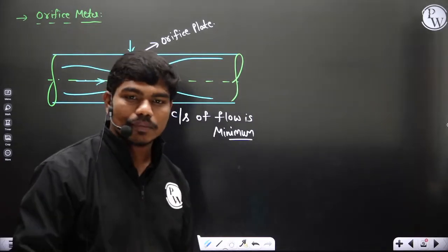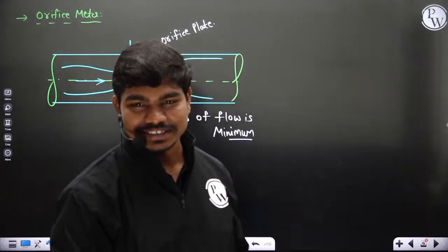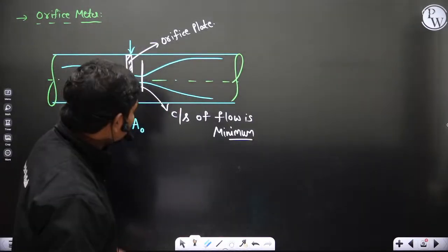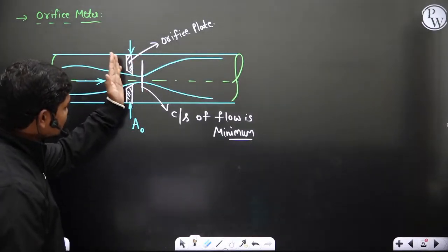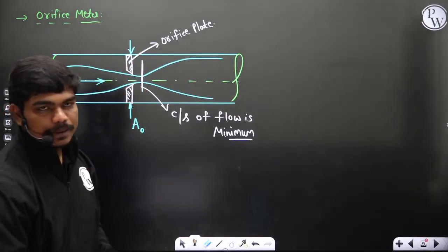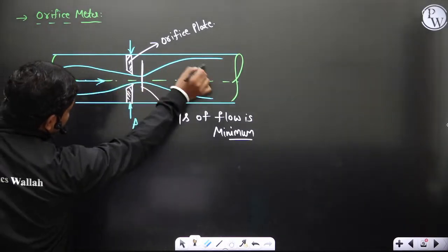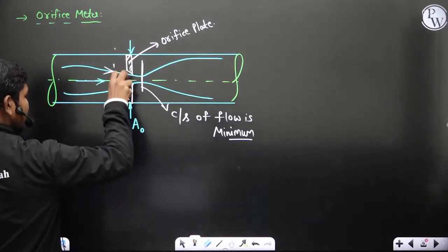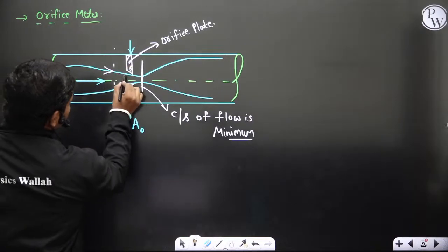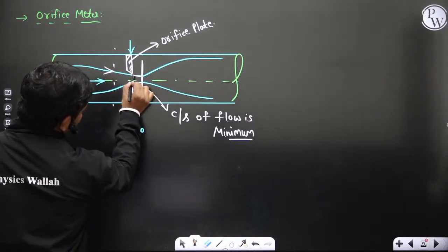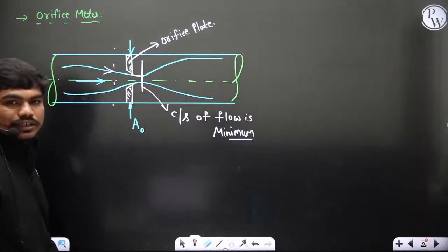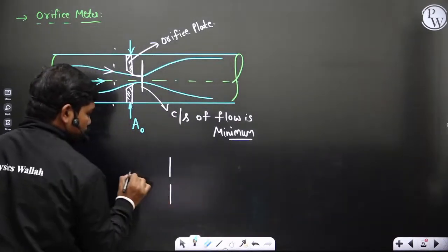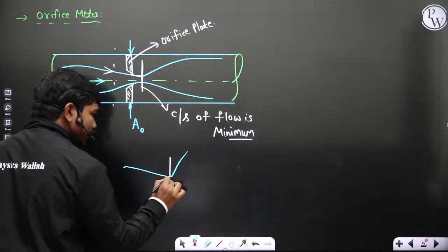If the calculation is complicated, you can use a bit of trigonometry, like we used in hydrostatic forces. Now see here, this cross section of the flow is minimum somewhere after the orifice plate, but not at the orifice plate. Whenever the fluid is flowing like this, for example if you take this as a streamline, when it enters this region it understands that there is a restriction in the cross section and it starts bending. Because of the inertia, it continues to bend for a small duration after the orifice plate. Immediately after the gap, the streamline cannot enter like this, it cannot expand the flow immediately.